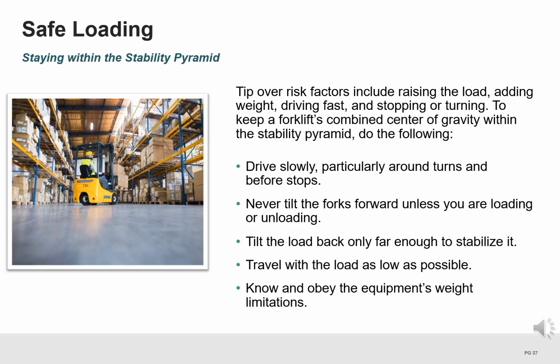Do not tilt the forks forward unless you are actively loading or unloading. Tilt the load back only enough to keep it stable. Always travel with the load as low to the ground as possible. And most importantly, know and follow the equipment's weight limits at all times.